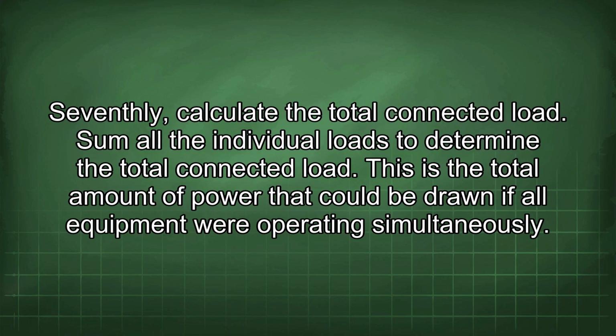Seventhly, calculate the total connected load. Sum all the individual loads to determine the total connected load. This is the total amount of power that could be drawn if all equipment were operating simultaneously.